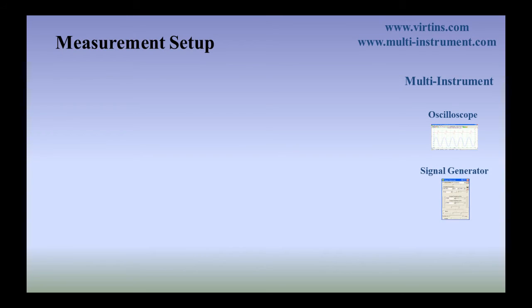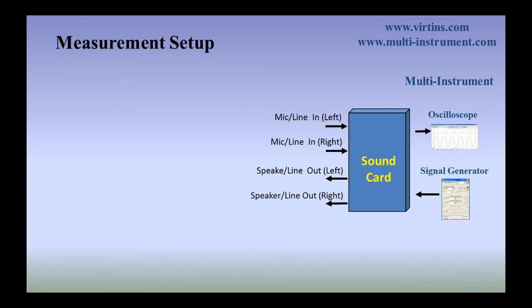Here, we introduce a polarity test method using the software Multi-Instrument, which can be downloaded from our website at www.virtins.com or www.multiinstrument.com. We will use its oscilloscope and signal generator functions. The hardware is a computer with a sound card.